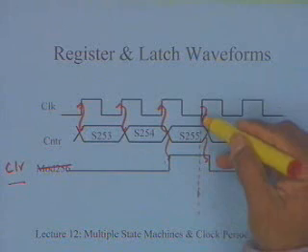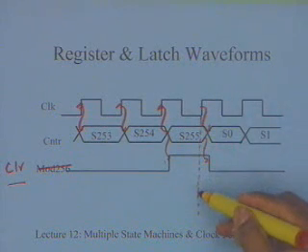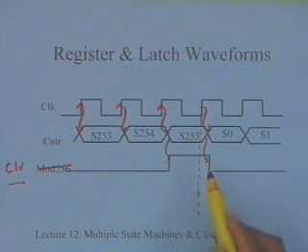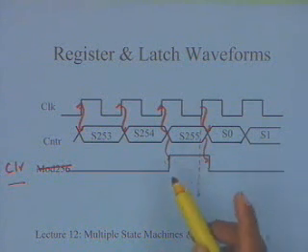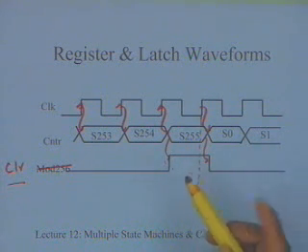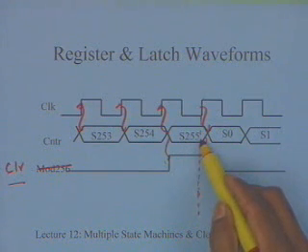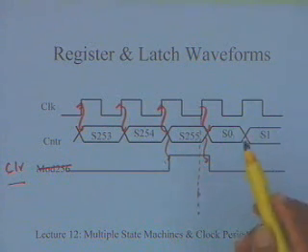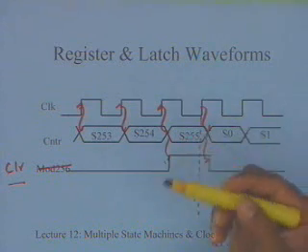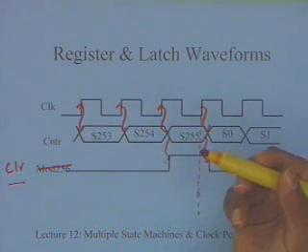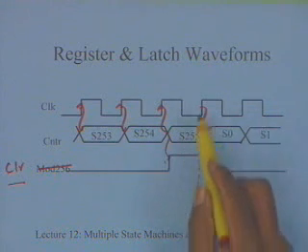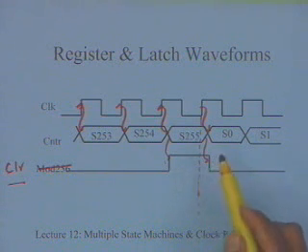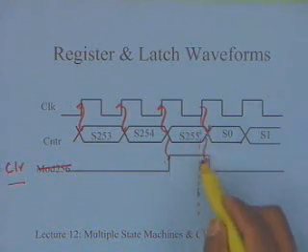And if you now look at the timing, it is at this clock edge that I will go to the initial state on the M2 machine, because it is going to get a clear and it is a synchronous clear. If I don't use a synchronous clear as we have considered before, I would have to generate not with 255, but with S0, because it has to do an asynchronous clear, it will immediately clear. But that will obviously mean that it will go to some other state momentarily and then come back to state 0, depending on where the transition is. So in this case, we are doing a synchronous clear with clear dominating over all the other inputs. The other inputs could be load or enable inputs, and so it actually will reach.